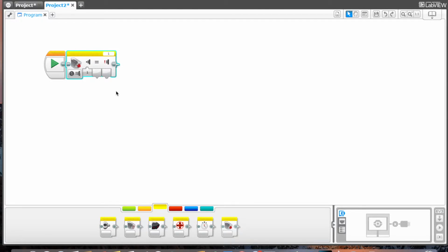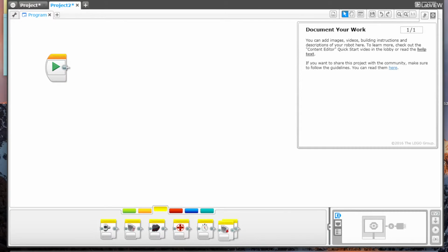The compare option offers more versatility, namely we can detect between three different states of the sensor: pressed, released, or bumped. Again, after selecting one of these actions, the sensor will expect that action to happen in order to trigger the next command. However, this block will output a true or false value and acts like a conditional statement. It can be used within a loop where we can check if our condition is true.